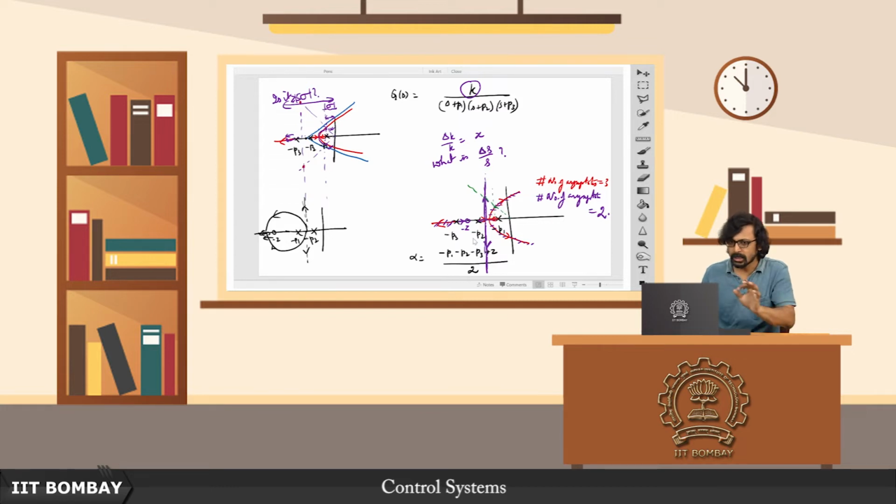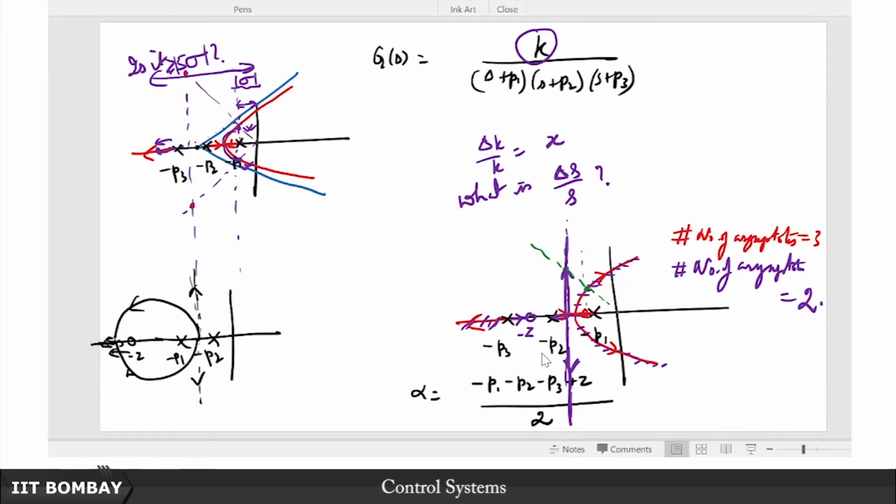But now, suppose you are allowed to play around with the location of this zero. Suppose it's like a sliding game, like a rheostat. There's some graphical user interface which allows you to slide this zero, and you are interested in asking what will be the effect on the root locus of the compensated system. So now we are forgetting about the uncompensated system with 3 asymptotes. From here on, our question is where to place this zero.